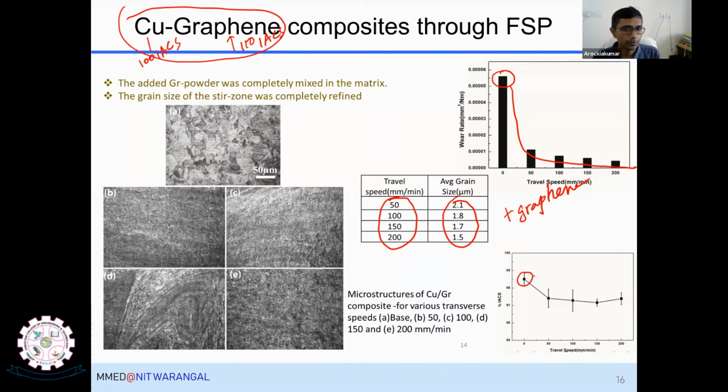It's a commercial pure copper, so it may have some impurity. Then its electrical conductivity may be less than 100% IACS, because impurity atoms hinder the movement of electrons, thereby decreasing the electrical conductivity. So that's why even this copper has around 98.5 IACS.